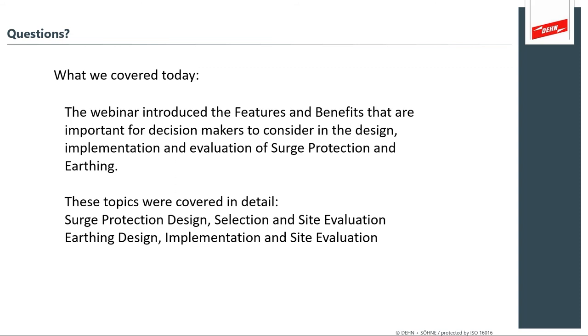Yes, as you mentioned, severed earth connections can lead to instrumentation problems. What kind of problems are we talking about? Well, a severed earth connection basically means that you're going to have unequal potential. So if there's a ground potential rise, the instrument will experience a different potential than the controller.